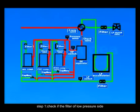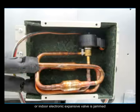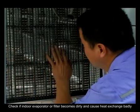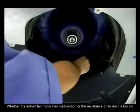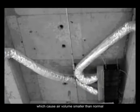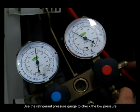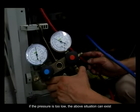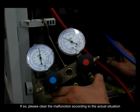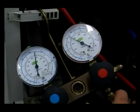Step 1. Check if the filter of low pressure side or indoor electronic expansion valve is jammed. Check if indoor evaporator or filter becomes dirty and cause heat exchange badly. Whether the indoor fan motor has malfunctioned or the resistance of air duct is too big, which cause air volume smaller than normal. Use the refrigerant pressure gauge to check the low pressure. If the pressure is too low, the above situation can exist. If so, please clear the malfunction according to the actual situation. If not, please go to next step.